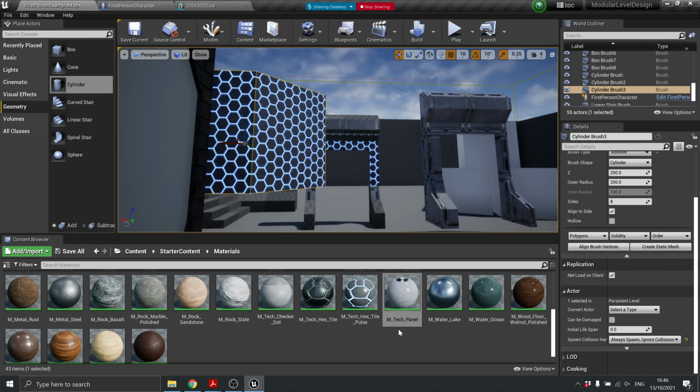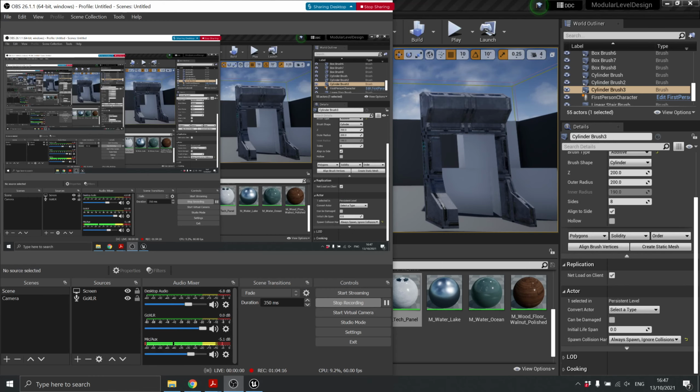This one, because that's a static mesh, the material will apply to everything. So if you want separate materials, put the textures on before you convert it to a static mesh. And then it'll save you. So, no worries. I will upload this.